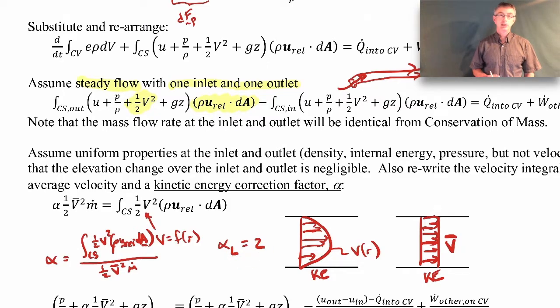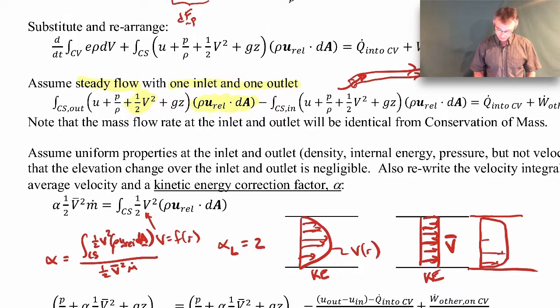If you're dealing with a turbulent velocity profile, we don't have a solution for that. But a turbulent profile will have a more blunt-shaped profile to it. Let me sketch that out for you. We know from boundary layer analysis of turbulent boundary layers that the turbulent velocity profile is more blunt-shaped. It's more average because of all the mixing that's occurred in the fluid. It's approaching more and more an average-looking profile.